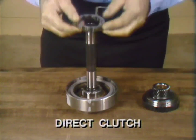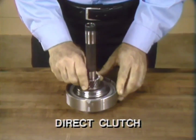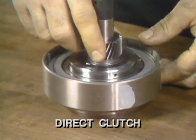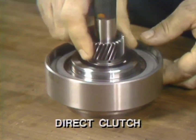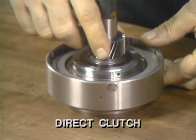You can see that the direct clutch completely surrounds the one-way clutch. Now, if the direct clutch is applied, there is no freewheeling. The turbine shaft continues to drive the low reverse sun gear, but the sun gear cannot overrun the turbine shaft. The direct clutch locks the shaft and sun gear together, and this gives us engine braking in manual low or reverse gear.